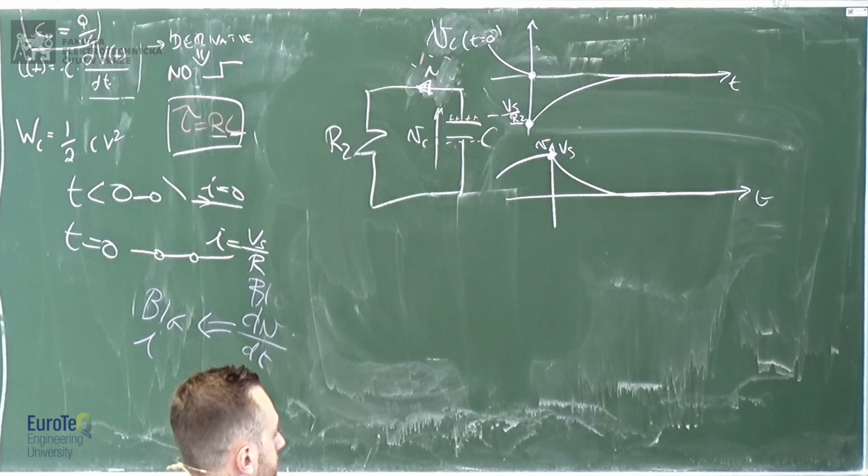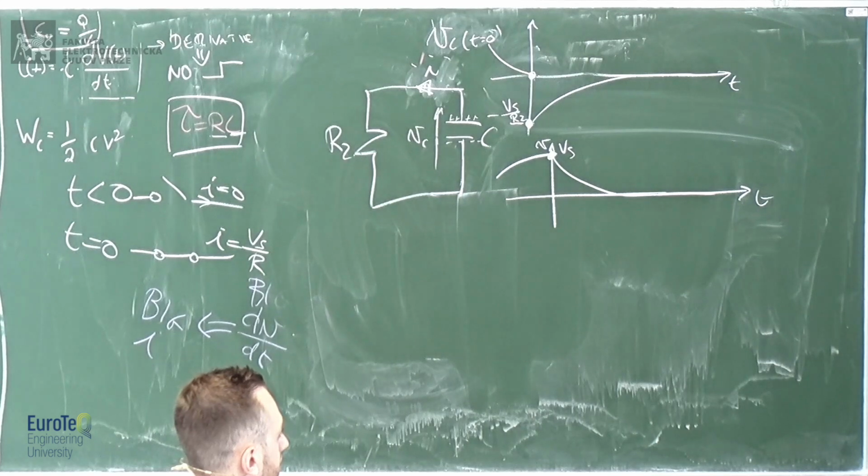I just remember that according to the packages, you have different values of inductance. I think, at least for SMDs, the bigger the package for a given value of capacitance, the bigger the inductance. I'm not sure, but those have tiny inductances because obviously they're small.